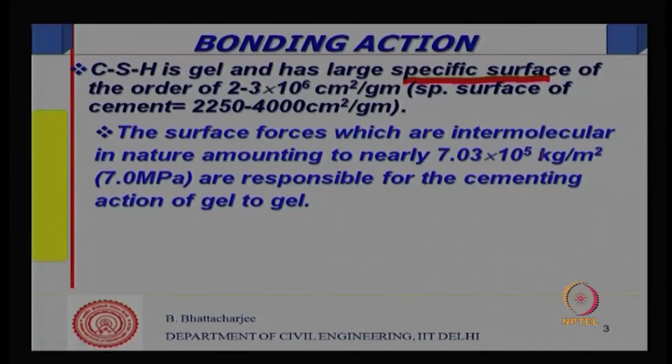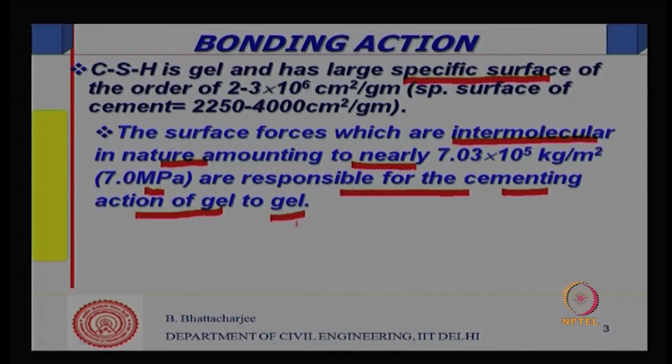Cement gel is very fine gelatinous particle, and therefore, very large surface area. Like clay, the intermolecular forces tend to hold them together. So, surface forces which are intermolecular in nature, of the order of around 7 MPa, are responsible for cementing action of gel to gel.